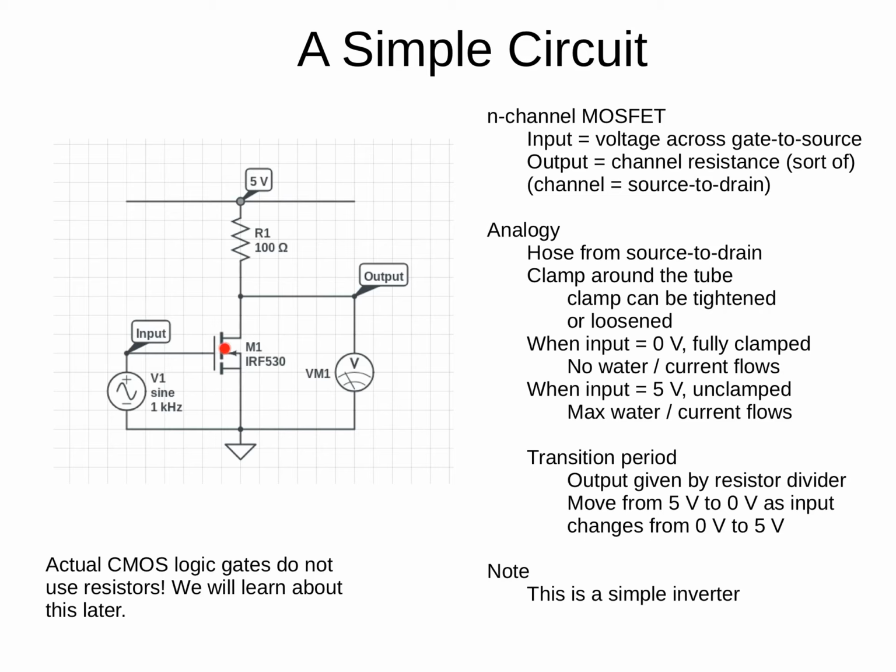Now of course it depends on the FET's characteristics, but for our purposes when we use FETs in digital design, we can assume by design that when the input to the FET is at the positive supply rail, then the channel is wide open. So when we've got a large voltage drop between gate and source, then the channel opens right up. Ideally it's got 0 resistance. In practice it's got a finite resistance, but anyway it's got a small resistance. And so we have a voltage divider here with 2 resistors, a relatively large resistance and a relatively small resistance.